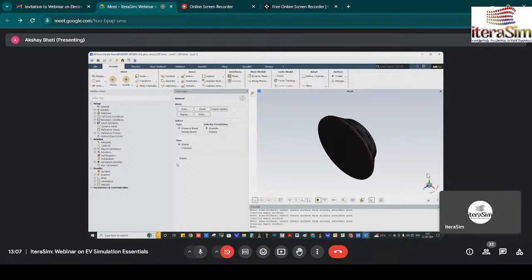Based on those constraints, you develop a rough calculation so that you can get an idea, applying the physics and theory of fluid flow and heat transfer for that component. Then you would have some rough dimensions. After that, you will design your fan and simulate it, because that is a 1D analytical calculation. It would never give you an accurate result. It would give results about 20 to 30% below or above.